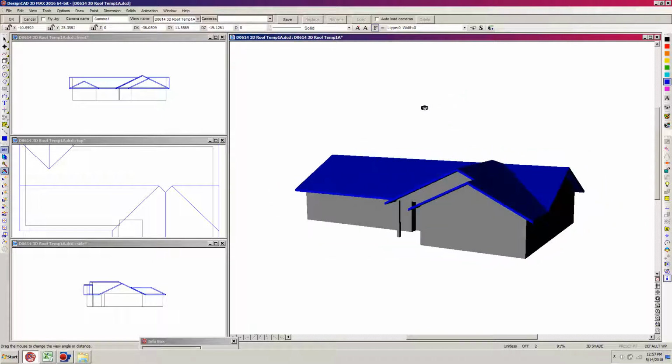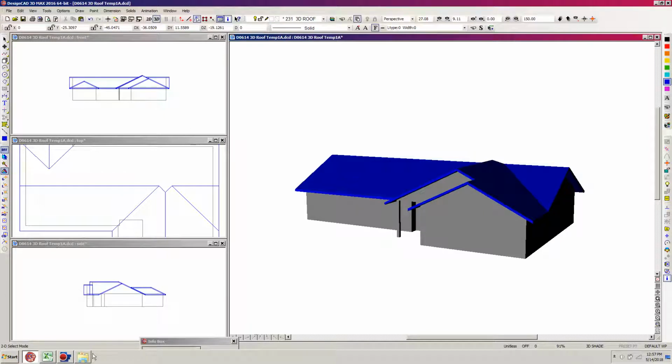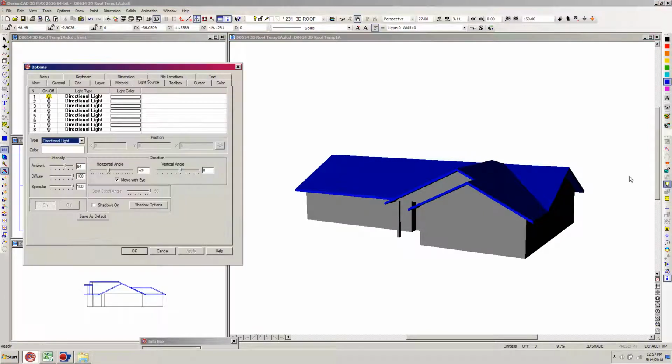The other thing is we can actually add more light to it if we want to. Click on the light bulb over here, and I can add an additional light to it, and change the location that this light is shining toward. Maybe this one I'll come over a little bit further to -40, and maybe down below a little bit to -6 or so.